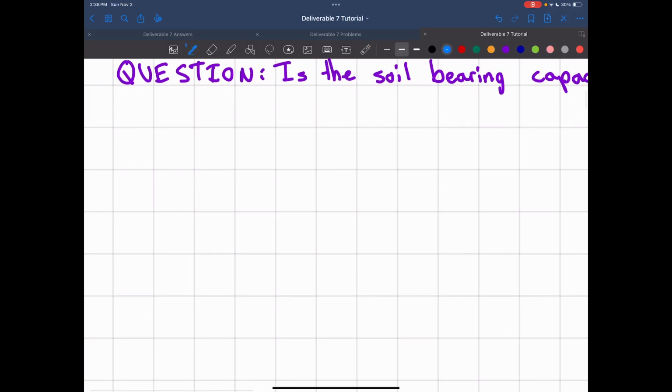So our equation here is pretty much the unit weight of the slab needs to be less than or equal to the allowable stress or the bearing capacity of the clay. Now, we also want to keep in mind that we don't want these numbers to be close, right?